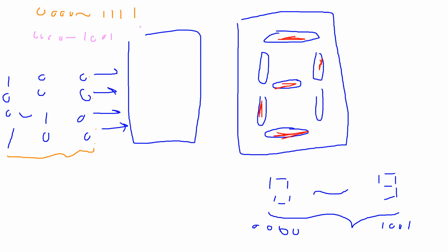If I apply, for example, 1, 0, 1, 0, how about the output? You don't know, right? But you don't care, because you don't use it. So in this case, the output for an input that you don't use is called don't care.